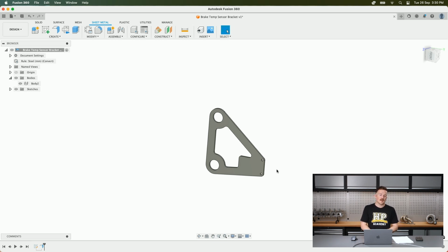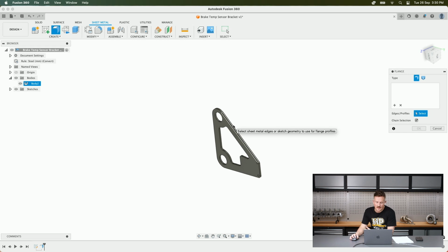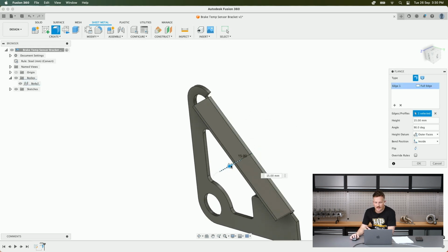So one way of stiffening a part is to add a bend or form the part. This is why dimple dies are used, for example, adding strength and structure to an otherwise flimsy sheet metal part. And bends do the same thing. So if we fold up a return along an edge, it goes a long way for stiffening the part, because you're essentially adding depth to it at the same time. So one way of using the flange tool is just to select it and click an edge like this, and then we can drag that out.